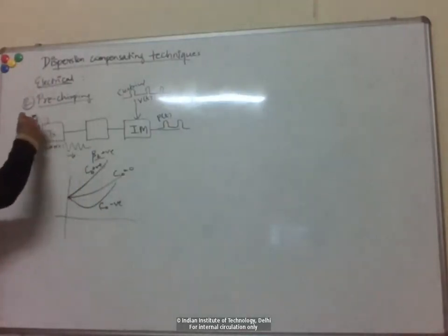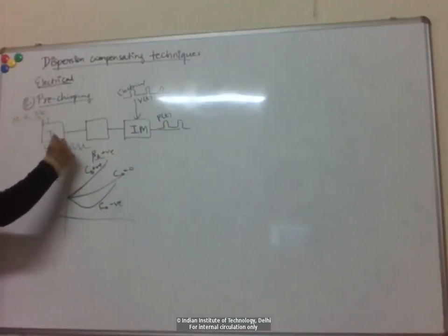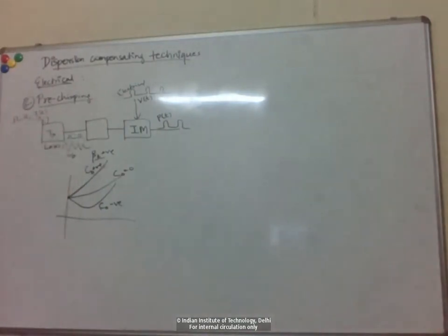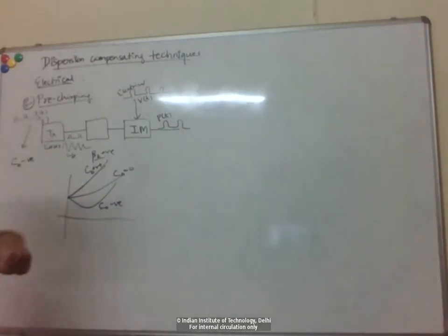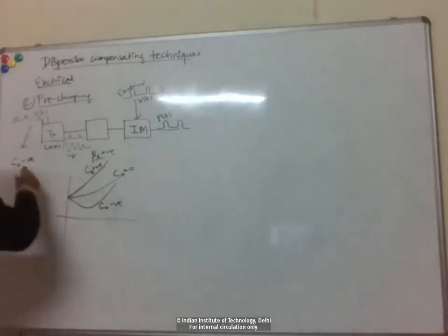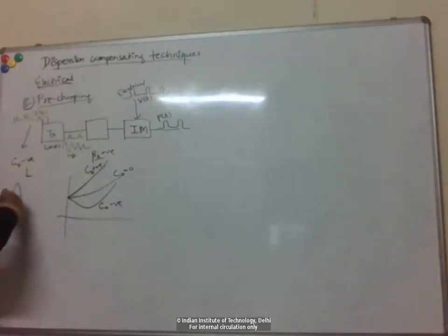You can also directly modulate the current into the semiconductor laser here, right? So you can have a modulated current like that to directly modulate the output power. That typically leads to a negative chirp. Okay. So if you directly current modulate the laser, just due to the carrier dynamics within the semiconductor material, you get what is a negative chirp, which is basically the carrier frequency decreasing with time within the pulse, right?